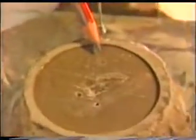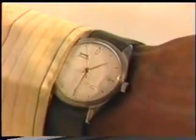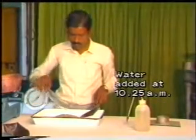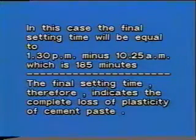After the elapse of initial setting time, observations with annular attachment are made at appropriate time intervals till the needle makes an impression on the mold while the attachment fails to make any impression. Final setting time will then be equal to the difference between the moment water is added to the cement and the time at which attachment fails to make an impression. In this case, final setting time will be equal to 1:30 p.m. minus 10:25 a.m., which is equal to 185 minutes. The final setting time, therefore, indicates the complete loss of plasticity of cement paste.